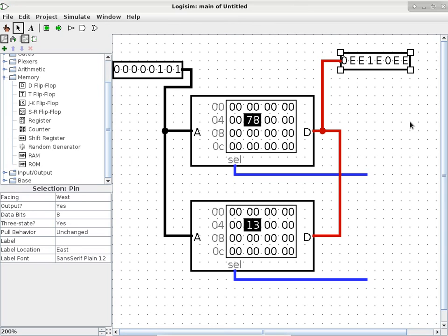Okay. What about the zeros and the ones? That means the 2 chips agree on those individual bits. So you don't have to fight over those particular bits. The E's are the ones where they do not agree. Let's just use this example. In the 7 of the 7, 8, it is in hexadecimal, and 7 is 0, 1, 1, 1 in binary, which is corresponding to this one over here in hexadecimal, and in binary it is 0, 0, 0, 1. So they only agree on the least significant one, which is why you have a 1 at the output pin. But the other 2 bits are different.